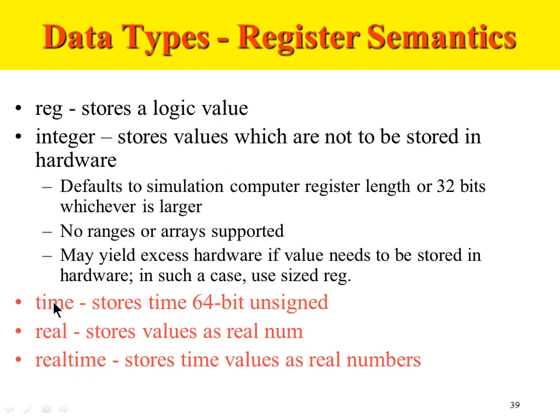But all these three data types mentioned last, time, real, and real time, are not synthesizable. They are only meant for simulation or testing purpose. So you can use it in a test bench. We will be writing a test bench to test our design, and the test bench is never implemented on the chip. So for testing purpose, I can use these data types in my test bench Verilog. But in my Verilog related to my design, I cannot use them because they are not synthesizable. This one is synthesizable, regular reg and integers.